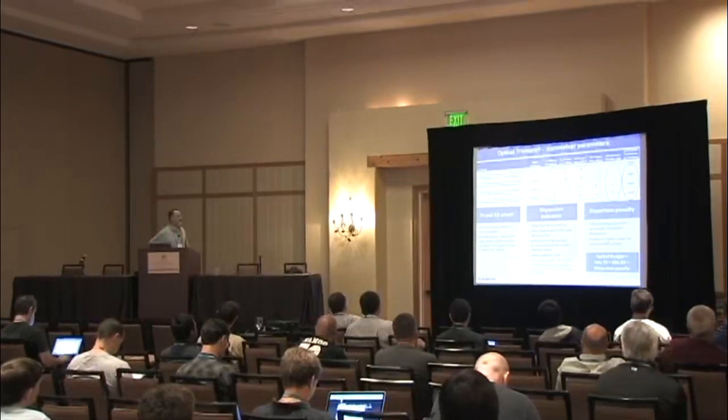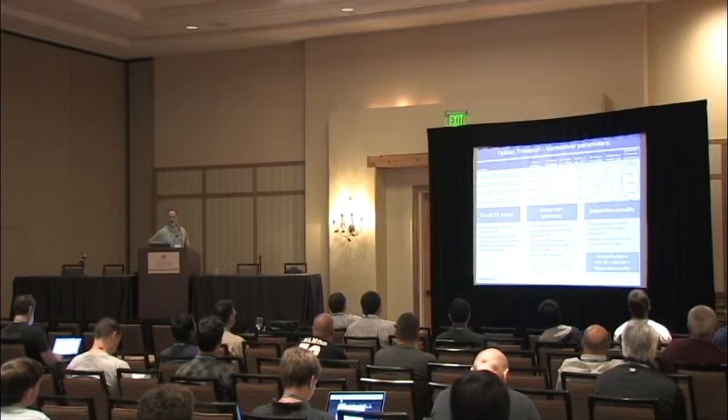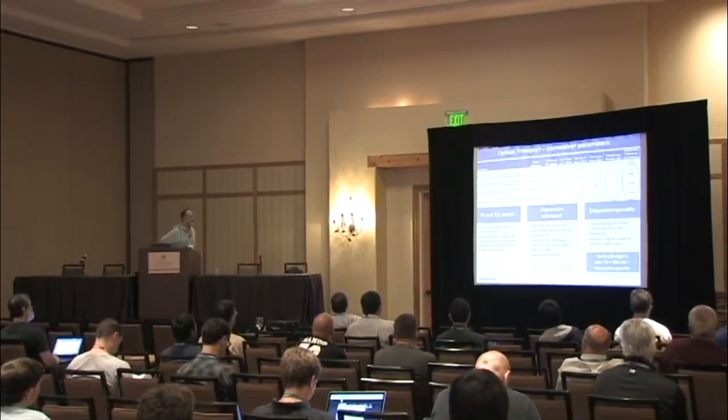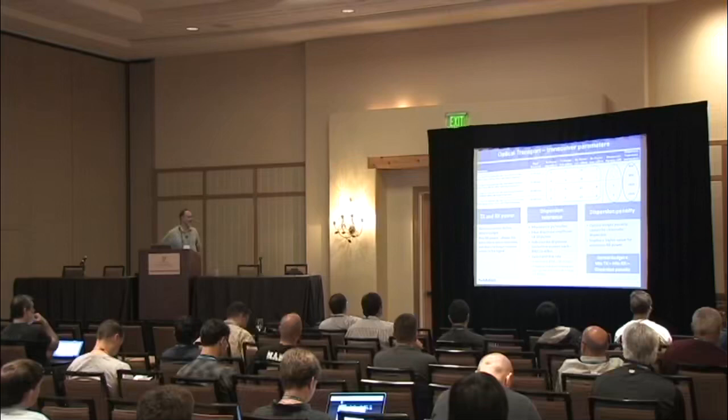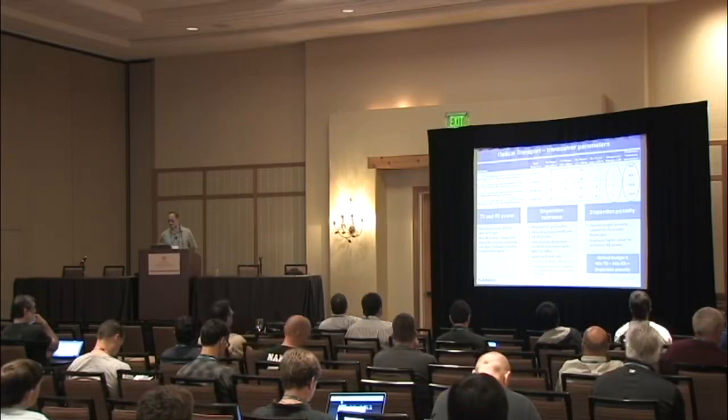Every type of fiber has a fiber dispersion coefficient. The standard SMF28 fiber generally has a coefficient of 17 or 18 to 20 ps per nanometer. And having a dispersion tolerance of 800 divided by 20 leads us to the 40 kilometer theoretical reach. And this varies with rate. This is typical for 10 gig Ethernet. If you increase it to use FEC rates like 11.3, the dispersion tolerance is going to be lower.